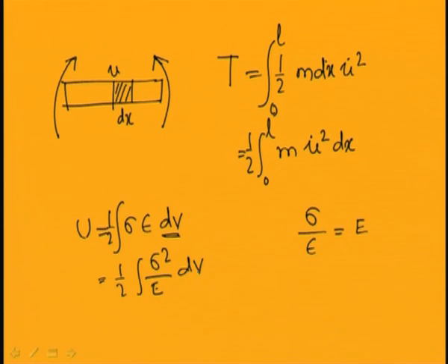So, this volume, elemental volume during bending. I can draw the cross section of the beam during bending. So, this is the cross section of the beam. This is the neutral axis. If I am considering a small element here, at a distance y from the neutral axis, of thickness dy, I can assume this width b is constant. So, this dV becomes b into dy into dx.